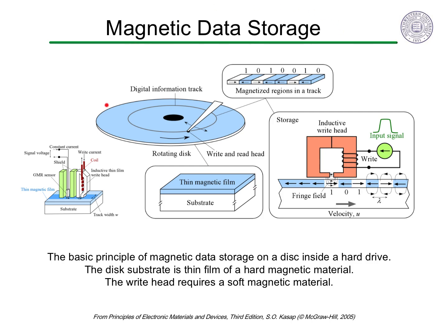Magnetic recording is still the primary method to store large amounts of data. Data is stored as small regions of magnetic domains written in a thin film of hard magnetic material. Data density now exceeds 1 terabyte (10^12) per square inch at a consumer cost of 3 cents per gigabyte. Soft magnets are used for writing the data. A magnetoresistive sensor is used to read the data.